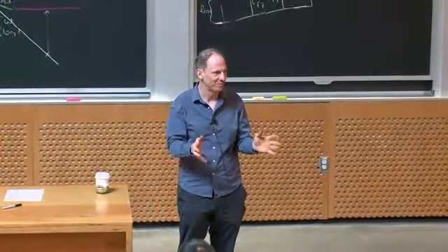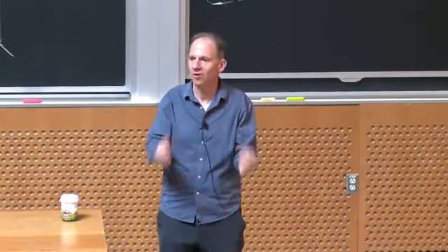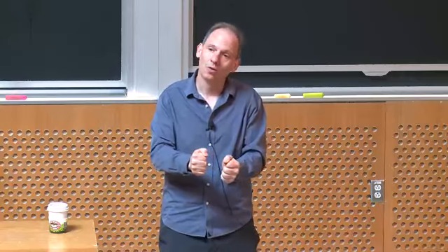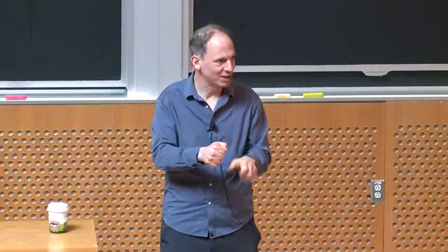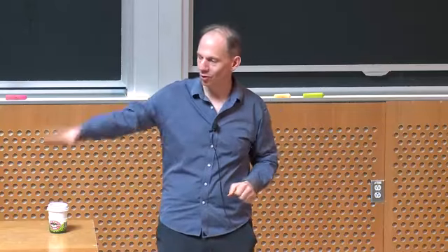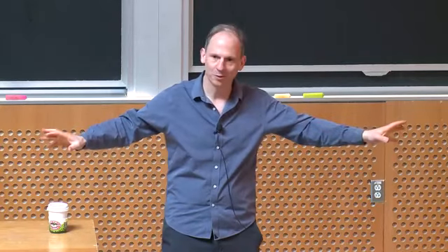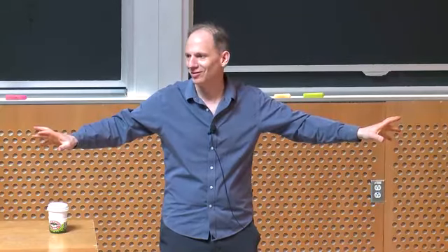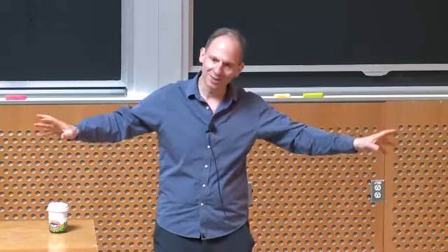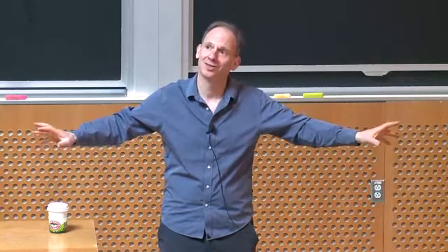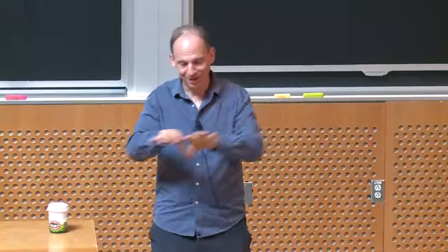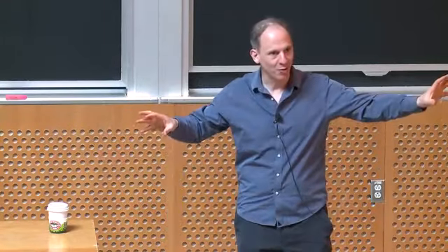Okay? So when you go out to do this stuff, the whole thing I want you to take away from this is really think about all the second order effects, the parasitics of the components and how you use them. And you know, we try really hard to do things like keep the noisy converter away from the quiet input we're going to plug into the wall. Some days you just can't get away from it because they tell you, oh no, can't change where our connector is, and just because the connector is right next to the noisy power supply, you're out, go figure it out, and you have to live with it. But if you can, try to keep your noisy stuff far away from your quiet stuff.